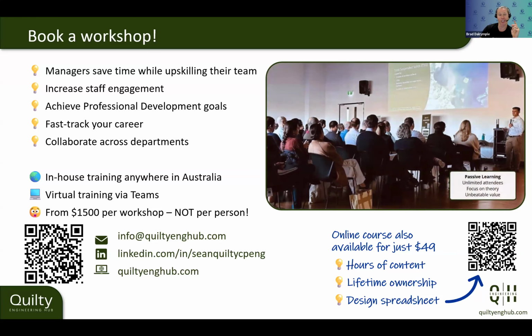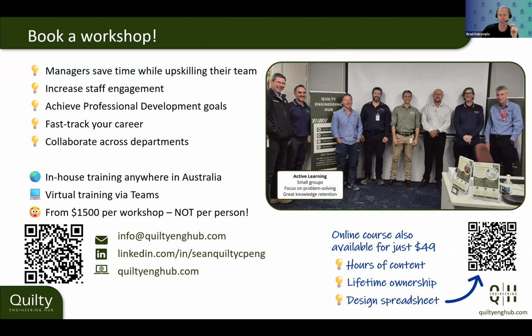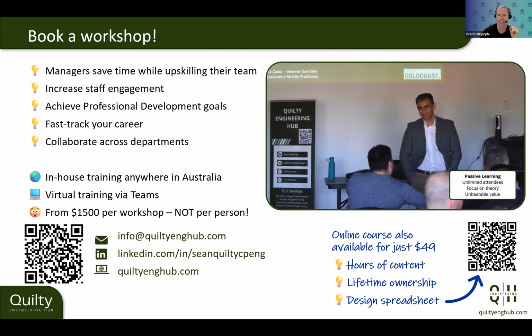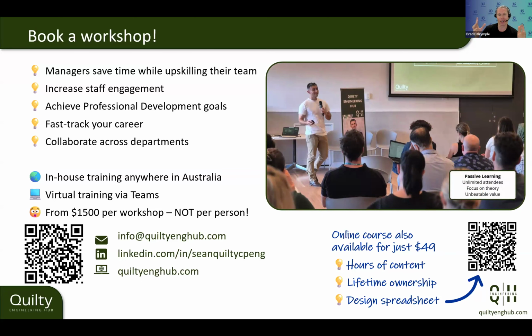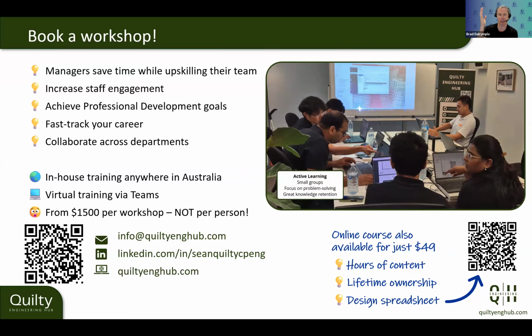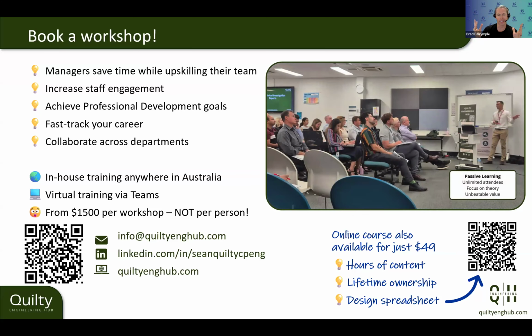But Yelena asked a really good question, and she's been very patient. Yelena asks, what roughness value would you use for a freshly built grass channel just after construction phase, when the grass is still establishing and it's prone to erosion? And this is probably a related question that I had. Vegetation changes. Sometimes vegetation will die back. Sometimes the vegetation can stand up to flows, but also sometimes fall over, like Lomandra. Roughness changes. So how do you design a channel that changes?